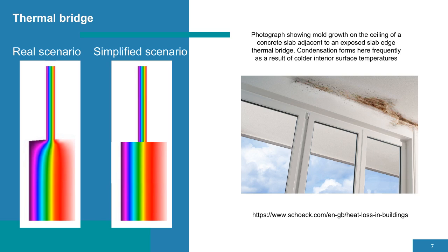In different connections, there are usually weak points in the building where the insulation layer is thinner or where thermally conductive materials cross the construction. Thermal bridge analysis provides information about temperatures at different points in the construction, allowing us to check if any points have a temperature lower than the dew point inside the building. Avoiding temperatures below the dew point prevents condensation on the constructions and the growth of mold.